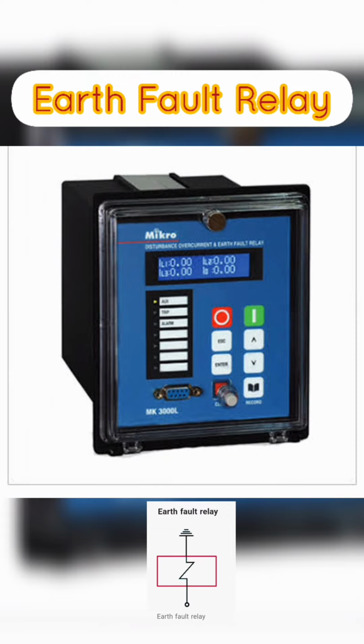The earth fault relay detects the flow of current to ground and initiates a trip signal when the current exceeds a predetermined level. The purpose of the earth fault relay is to prevent damage to the equipment, reduce the duration of the fault, and protect personnel from electric shock.